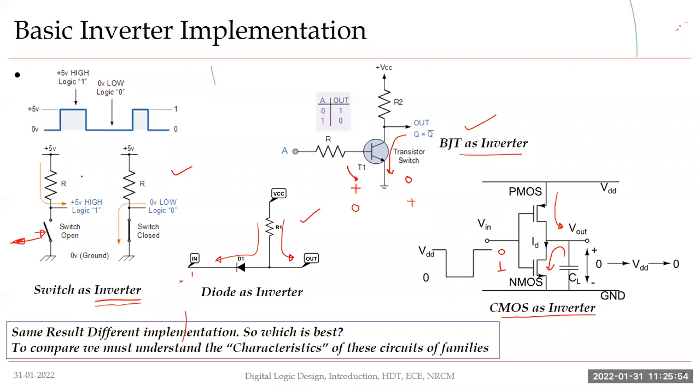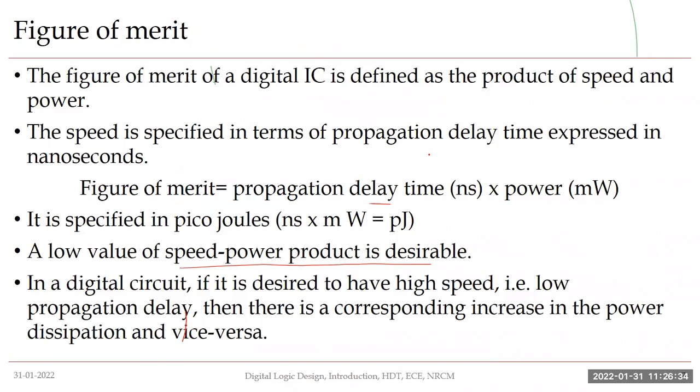Let's see the circuit operation here one time. Here my VCC is going to give the current to the other device. This is called current sourcing. We are going to source current to another device. But when I am discharging, the current will come and go through our device. This is called current sinking. We are able to sink the current. So in one case we are supplying the current, in another case somebody else is supplying the current to us. Source current and sink current.